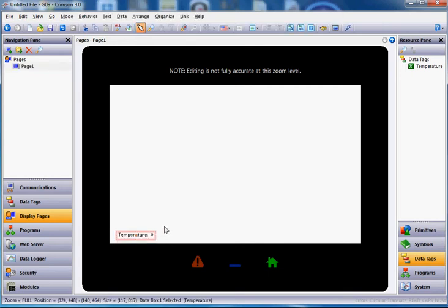And then here's a shortcut I always show off in class. If you take your mouse and click somewhere else so you don't have focus on anything, and then take your mouse and just hover over this particular tag, if you click one time, the little ghosted shortcut box should come up, and this button here will make the font much bigger, and this button here will bold it. Now click away. Notice the hazard signs. All that is telling me is that the element inside this box is too small, so I'll just click on this thing and I'll grab one of the corners and I'll stretch it a little bigger like so, just so it's a little bigger like that.